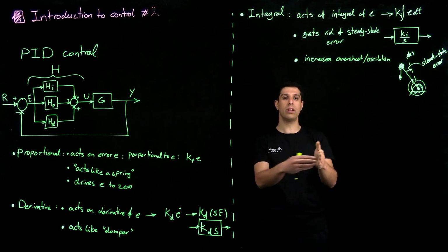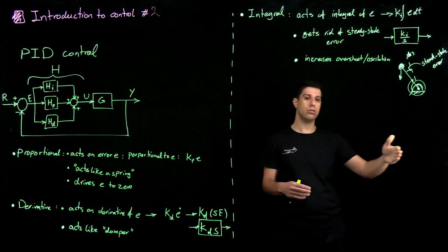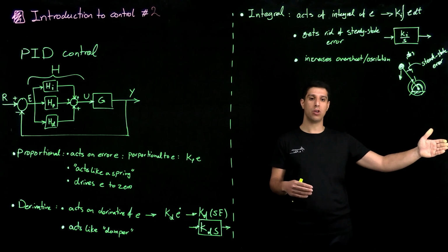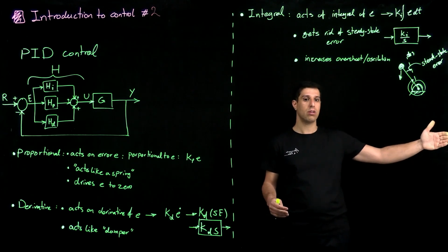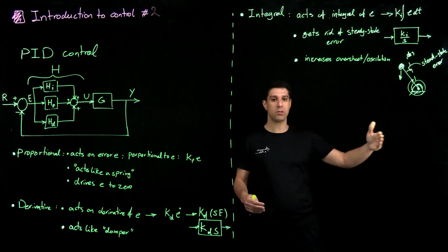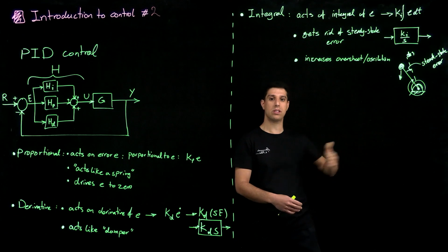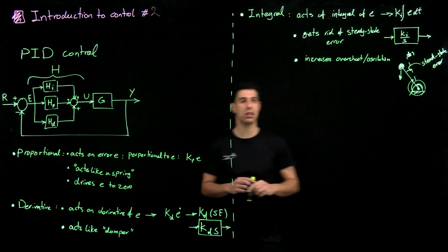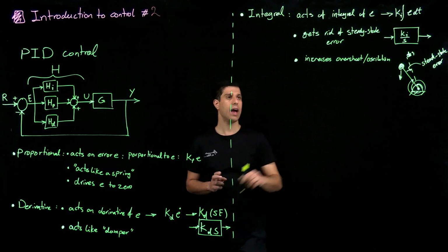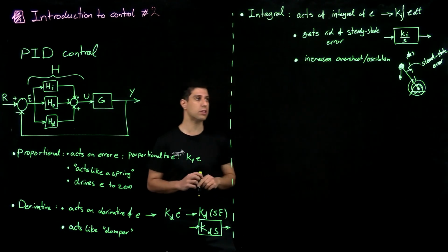So your control is still pushing the system forward. So it overshoots. Now you're accumulating negative error until it's 0. And then the system comes back. You have these negative errors, and the system goes back and forth because you are integrating the error. And the same effect is involved when it increases the overshoot.